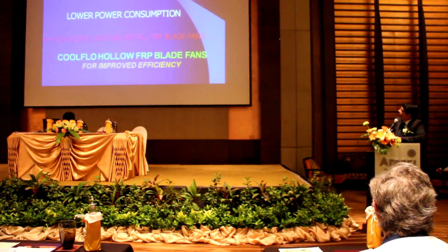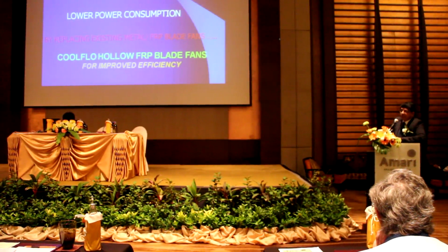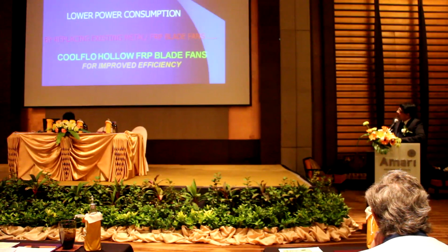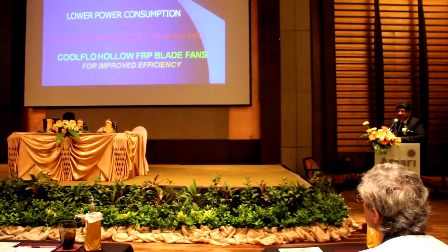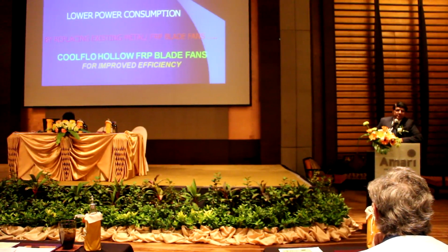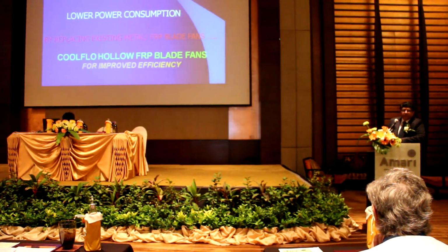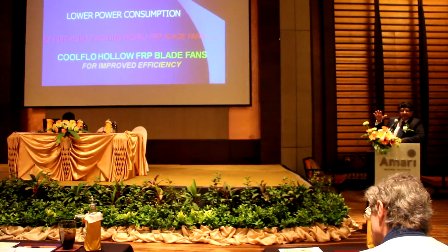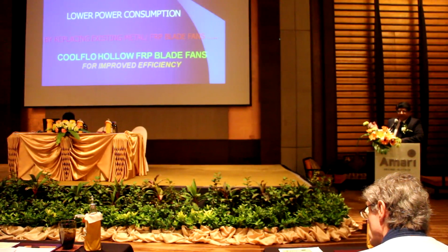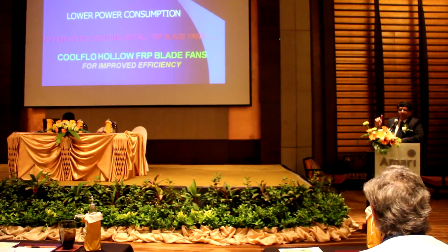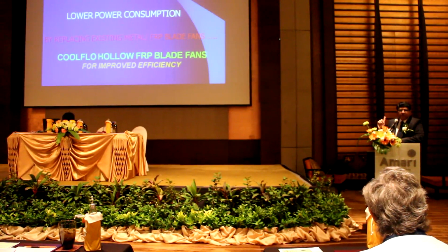We have achieved higher airflow in fan coolers. We have seen that with better design systems, there are lower vibrations, low noise and lower power consumption. Some of the specific cases I would like to mention: when we gave them fans for increasing the airflow, the thrust achieved by our fans was so much better that it gave them the higher airflow, but the structure which supported these fans could not take the higher thrust.